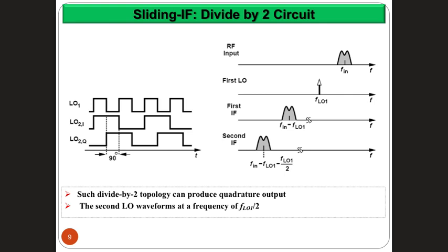It talks here about the fact that in the design of those frequency dividers, they can actually do dual functionality, so they can do the division of the frequency and also produce the quadrature and in-phase pieces. So it produces two versions of the oscillation signal, one is a cosine and the other is a sine carrier, in a single component.